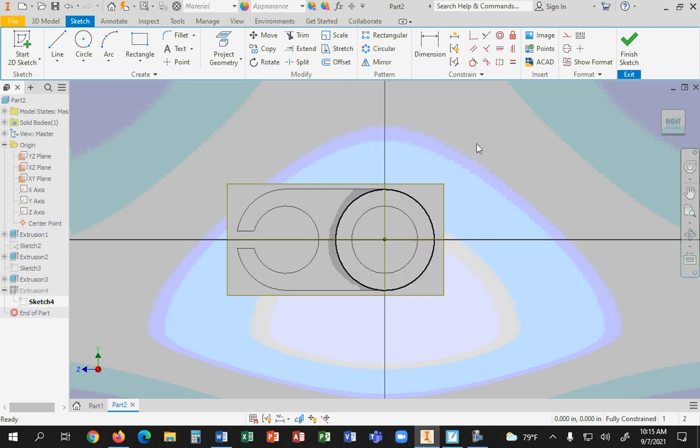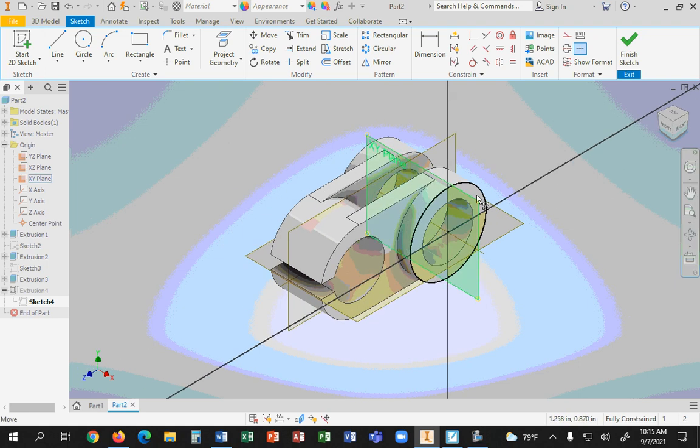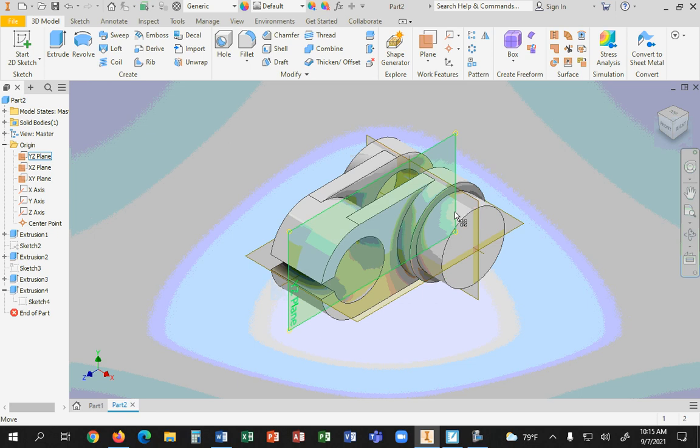In your case, though, if you want to get rid of a constraint, you have to first see them. So you have to visually see those constraints. When you click on the object, that's when you see their constraints. So you could click on that guy and say, no, I want you to delete and go away, so that I can control you independently. See that? When you do stuff like that, then you can add steps and things like that. Cool?